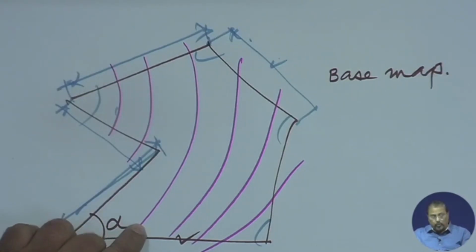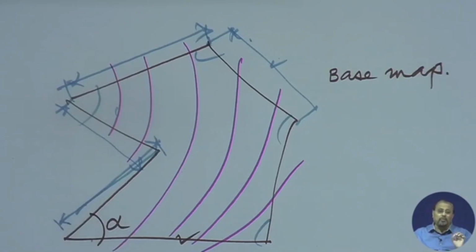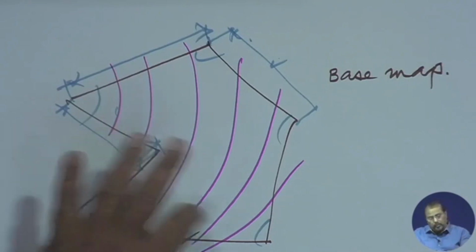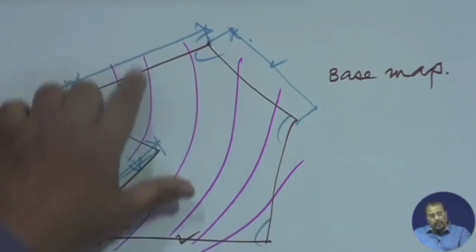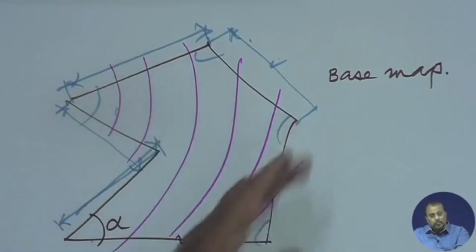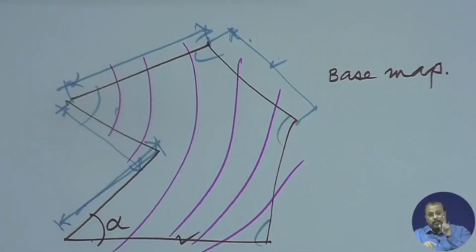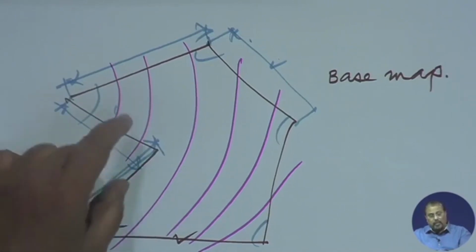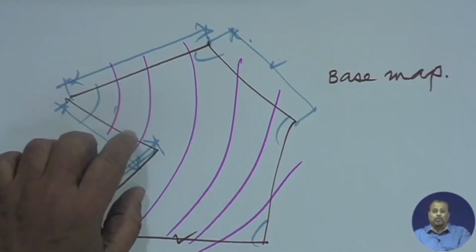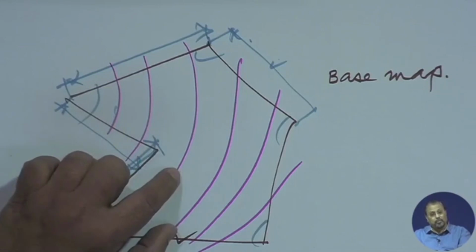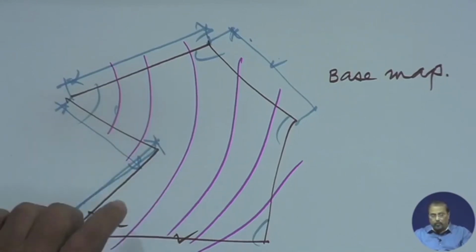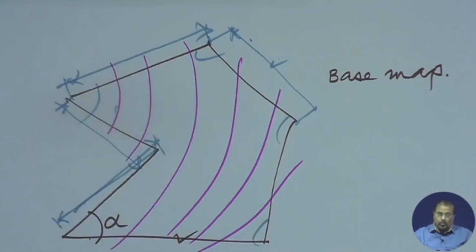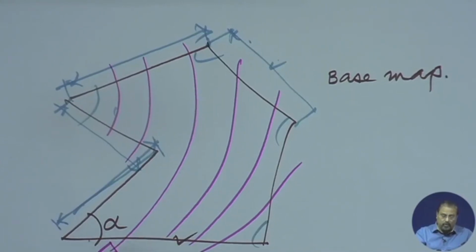How will the surveyor do it? He will find out the spot elevations of different portions. It may be done uniformly with grids, and at the intersection points he will find the spot elevations, and then from there interpolate or extrapolate these contours. And once he gives you the contour lines, he also has to give you a level.